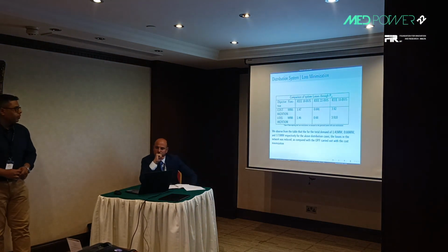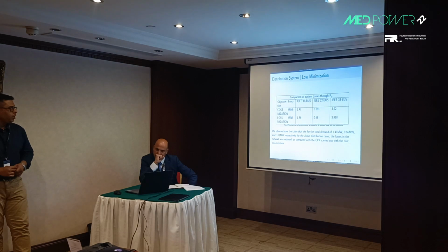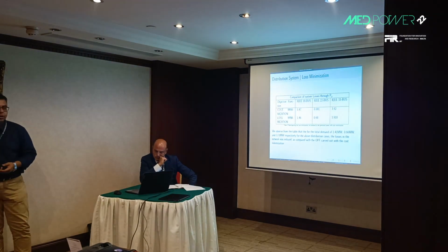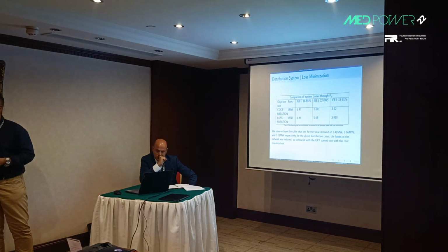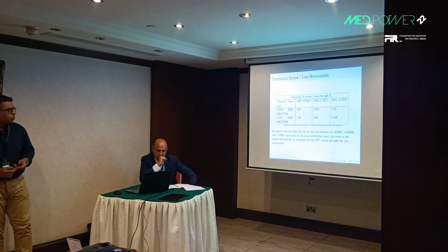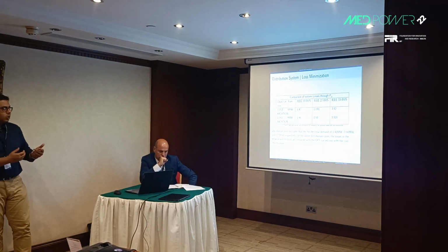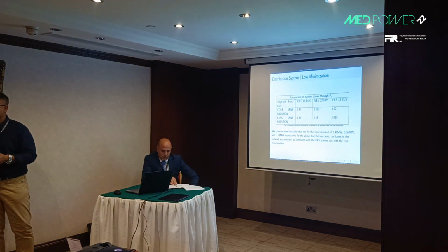Going further, for the loss minimization, we have very minute loss minimization because this is a distribution network and we haven't considered any bidirectional power flows. Since it's a unidirectional current flow, the loss minimization is only limited to limiting the voltage bands of the network.